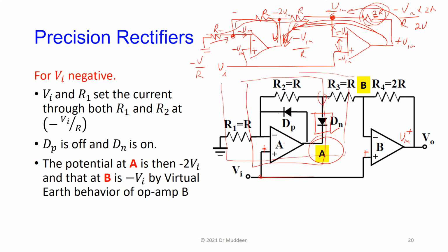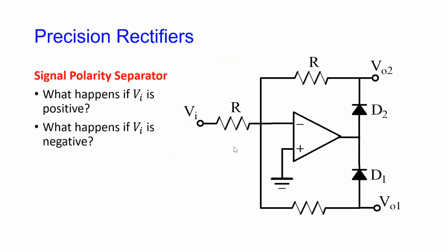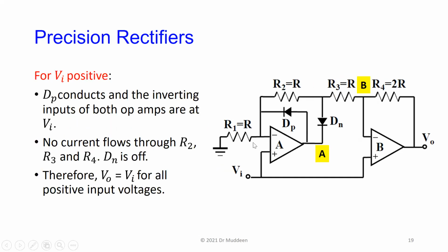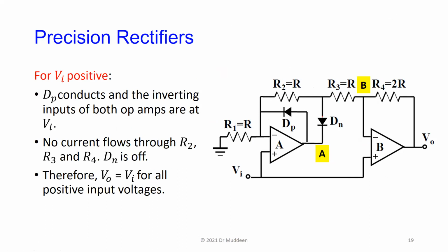Dn being open circuit basically means that there's no electrical connection. If you were to take this out, there's no connection here at all, right? And this is a short circuit here. So if you short circuit this and you have no connection inside of here, it means this point is not connected to the circuit. So this op amp just has a floating output.